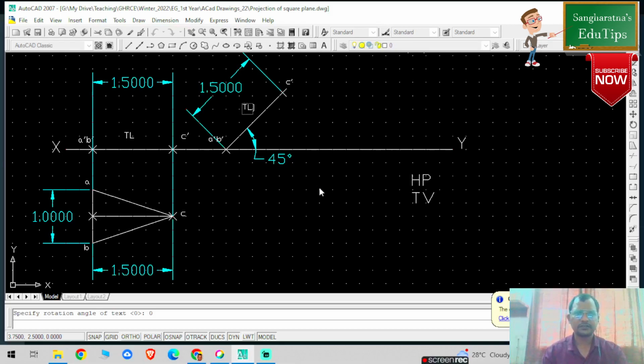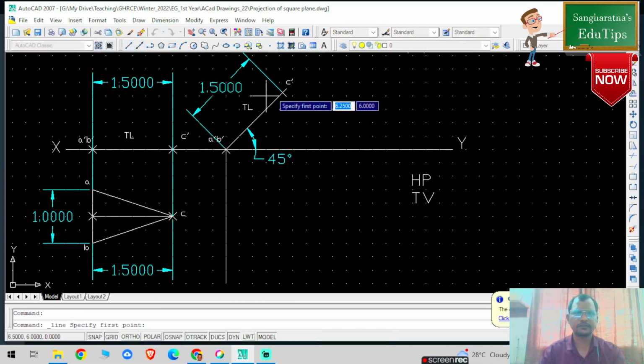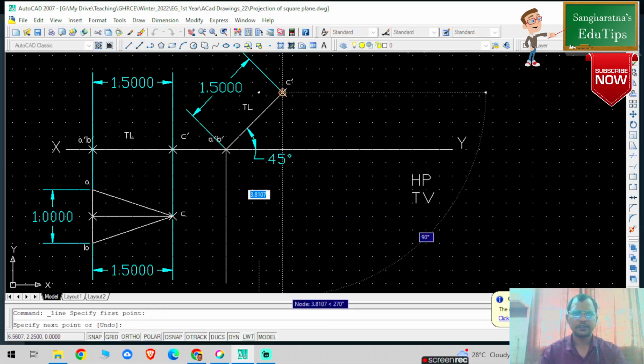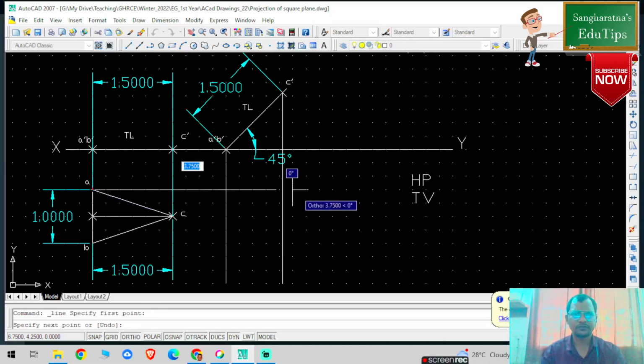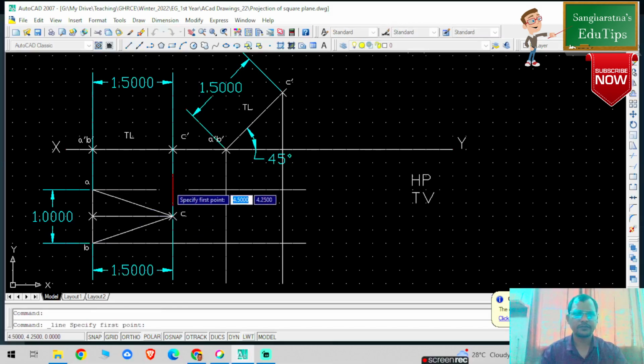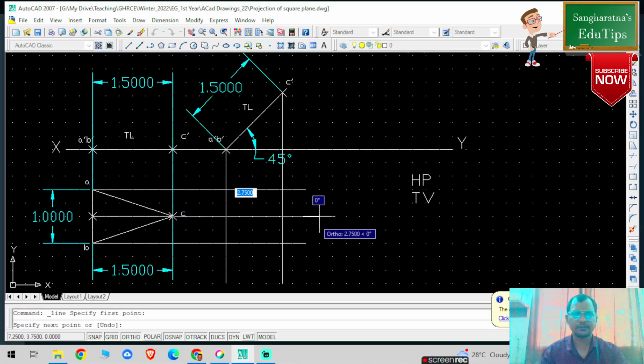Yes or no, right? Select and set, and then draw vertical projectors from this particular point. You might have observed all the steps are similar to the case of projection of planes. Now we are not going to the third step. The third step is basically the auxiliary inclined plane method. For your syllabus we are actually coming towards the two steps. Now from this particular point I'm going to draw one projector, from this particular point another projector, and from this particular point C another projector.